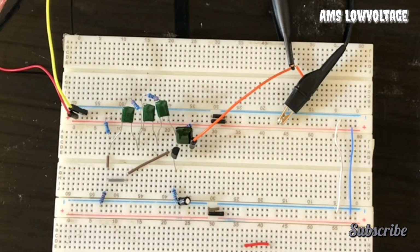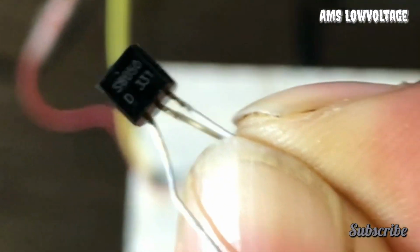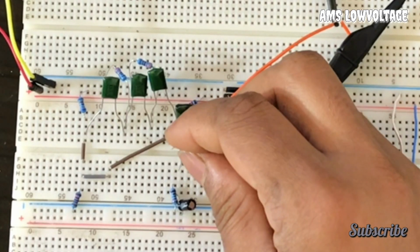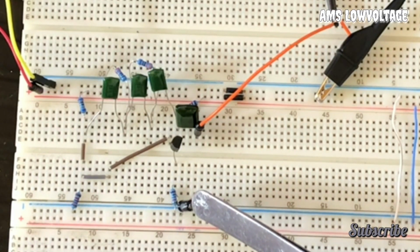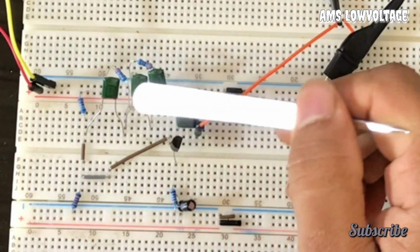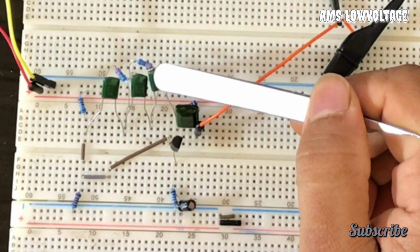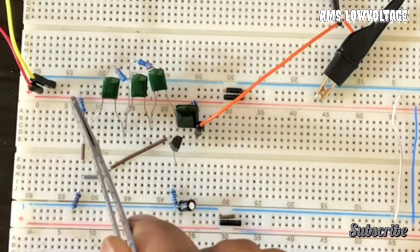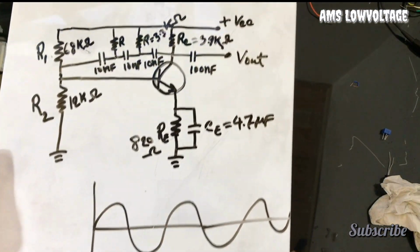So here is my circuit placed on the board. This transistor is an S8050, an NPN transistor. I have used 2N2222 transistors before, but for now I'm using this transistor. This is 4.7 microfarad, and 820 ohms, 3.9 kilo ohms, and this is the positive feedback loop circuit. Each of these resistors is 3.3 kilo ohms, and each capacitor is 10 nanofarad, and this is the biasing resistor, 68 kilo ohms. It's exactly as it is in this circuit.